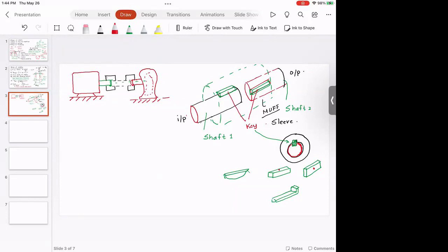these shafts together. For example, if I have a motor shaft and a pump shaft, I cannot weld them together. That's not going to work because first and foremost, welding would cause an enormous amount of thermal stress. It will break the seals. It will start leaking. It will reduce the life of the component. And also it will not maintain the circularity and concentricity that are required for proper operation.